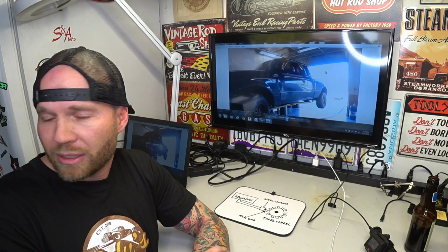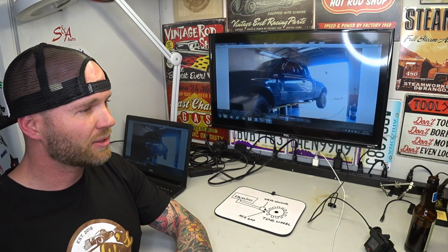It was the very slow braking, and the customer nailed it. The last 5 feet of braking under 3 miles an hour, the ABS would activate. If anybody knows what the ABS feels like when you're stepping on the brakes, the pump runs and it pulses the brakes. Anyways, so I verified the customer's concern, and their description of it was pretty spot on.